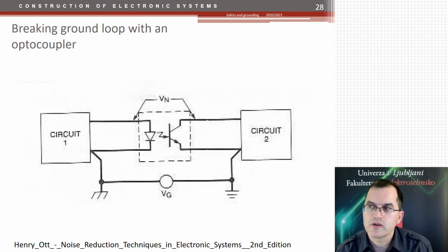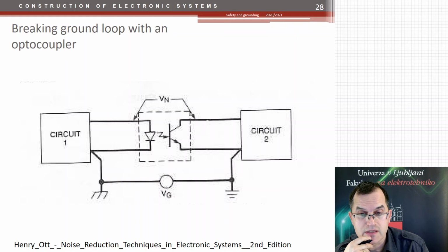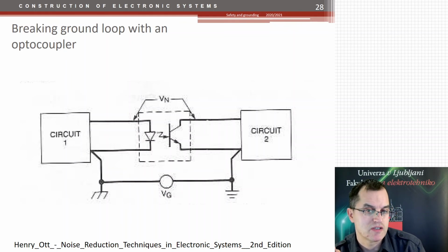The optocouplers, on the other hand, are not that often used for that purpose. They are, but their problems are that they have a lower frequency range, and the lifetime is not that good as well. But they are often used in lower speed communication systems.